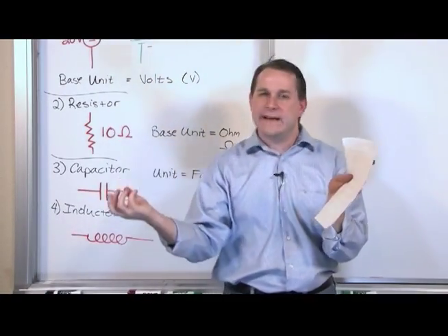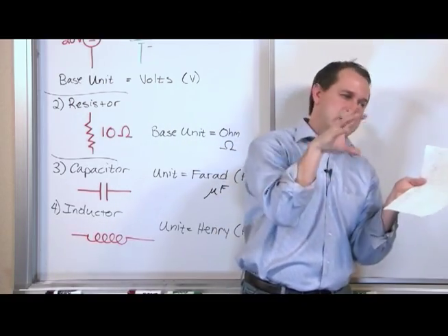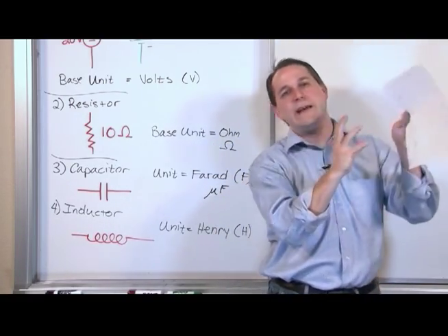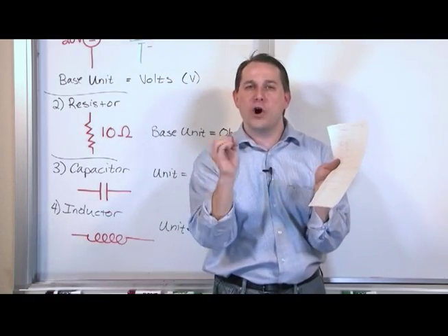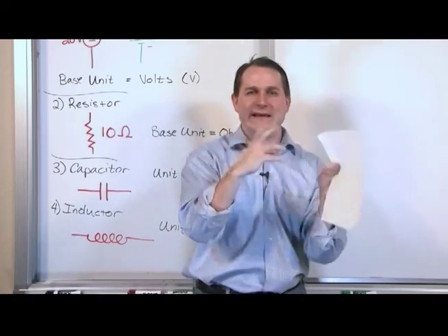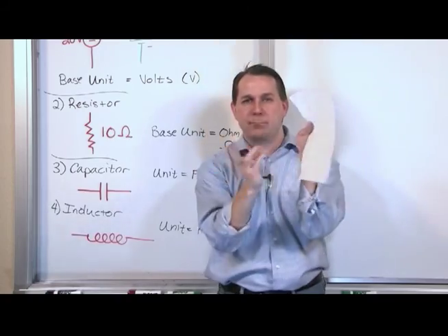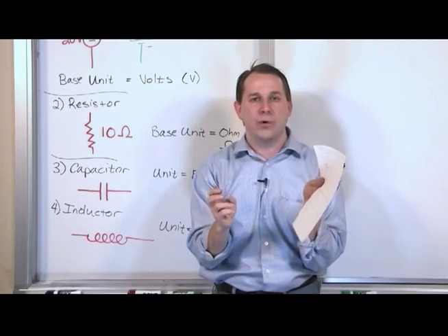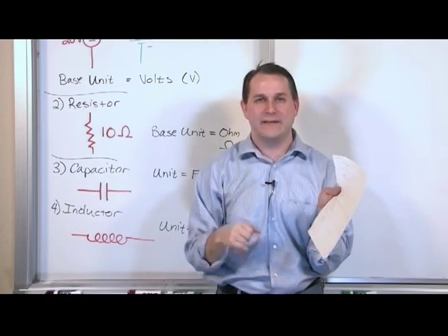The capacitor sends energy into the inductor, and the inductor kind of collects that energy. And then on the next cycle, it sends the energy back to the capacitor. And it goes back and forth in this perfect harmony. It's called resonance. It's very perfect harmony when they kind of send this energy back and forth. And at that moment of resonance, when they are both doing that perfect dance of sending energy back and forth, that is the frequency of the wave that you're receiving, and that's what gets sent to the speaker.